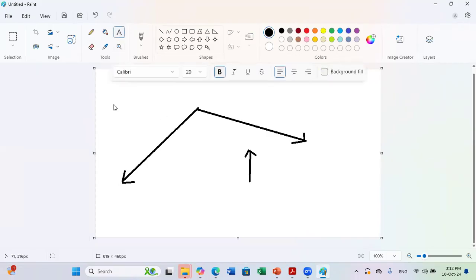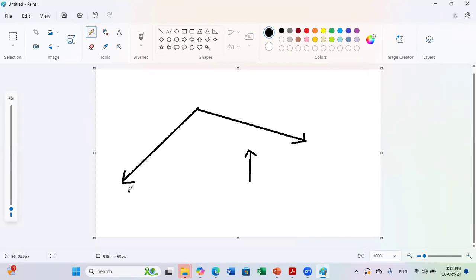I have three axes, x, y, and z. And my force is only along z. It has only a component along z. Since it's parallel to z, can it produce a moment about it? No. So first you say for F1, no moment about z. Now, F1 can produce a moment about y and a moment about x. To find these moments, you extend the line of F1, okay? And you find the intersection on the XY plane, okay?